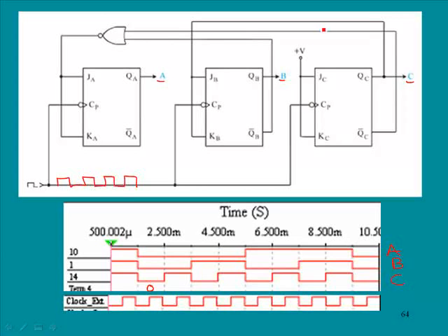Now, of note, we have a positive voltage here, and so that will put a high here and a high here. And so what will happen is that flip-flop C, which has output QC right here, will toggle on every clock pulse that comes in. This has little bubbles here, and so you'll notice here we have the negative edges occurring here, here, here, and all the way across.